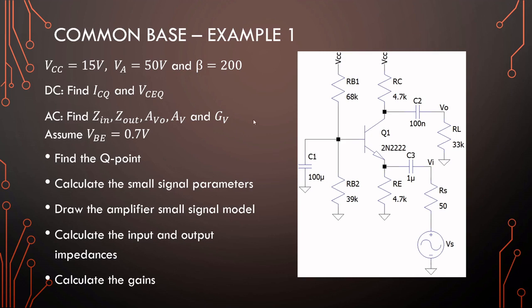so let's look at this for the DC analysis first, and that will be the last time that I look at the DC analysis for this amplifier type. There are only going to be 3 examples on this. There are not so many variants. The only variant is going to be the biasing structure in the end. So for DC, this capacitor is going to be open circuit, this cap is open circuit, this cap is open circuit, and what do you see? Plain voltage divider bias.